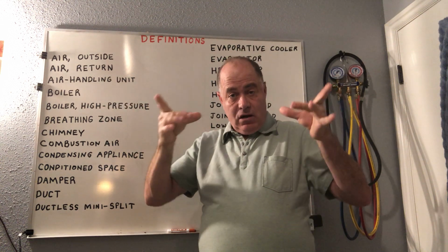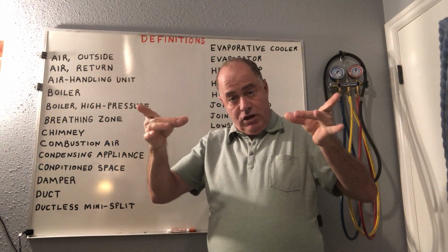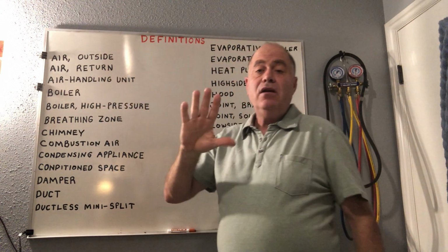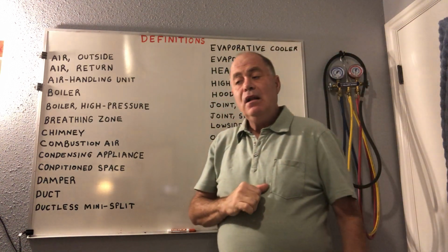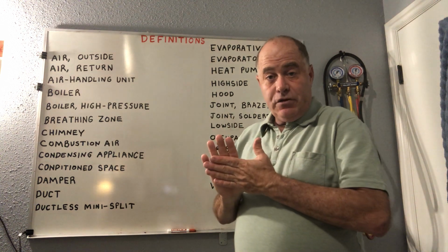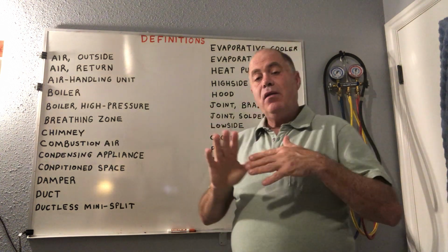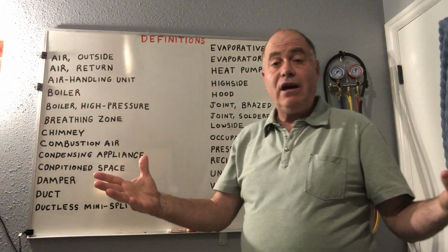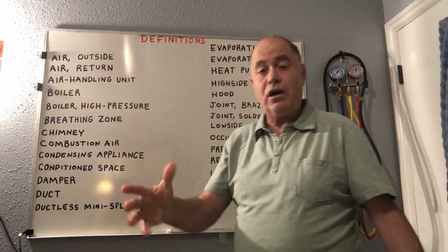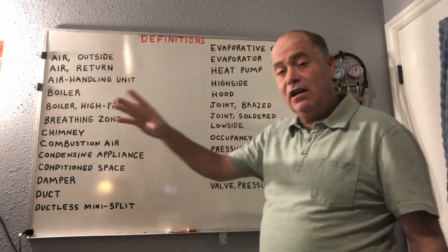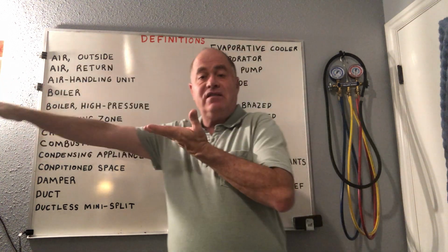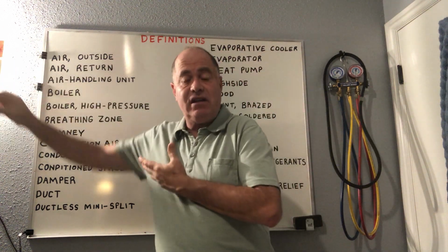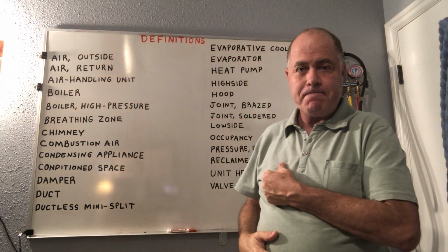They're thin little units, and they provide heat, hot air or cold air, and they have a filter there, and they don't have any ductwork, so you don't have any losses through the ductwork. And then they have some refrigerant piping and electrical that go outside to a condensing unit that sits outside to get rid of, let's say, the heat when you're in the cooling mode.